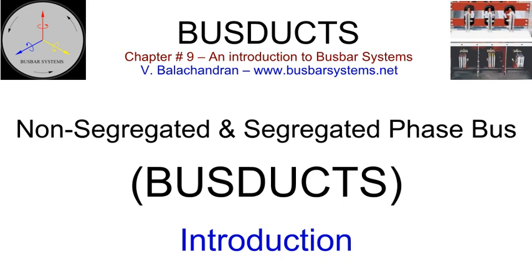An arcing fault will ionize the air in the vicinity, and depending upon the intensity of ionization and time, the ionized gases can spread to the neighboring conductor, resulting in a phase-to-phase or even a three-phase fault. If the ionized gases due to arcing can be confined to a limited area by the introduction of a phase barrier between the two phase conductors, then the probability of a ground fault developing into a phase-to-phase or a three-phase fault can be minimized. Installation of the phase barrier can increase the factor of safety to a considerable extent. If the intensity of the arcing fault is high, the arc may penetrate through the barrier and initiate a phase-to-phase or a three-phase fault.